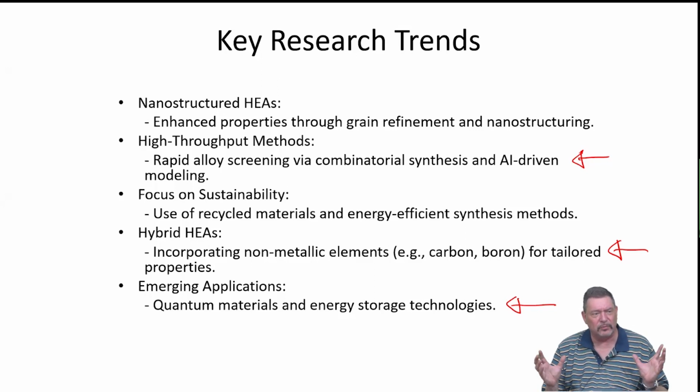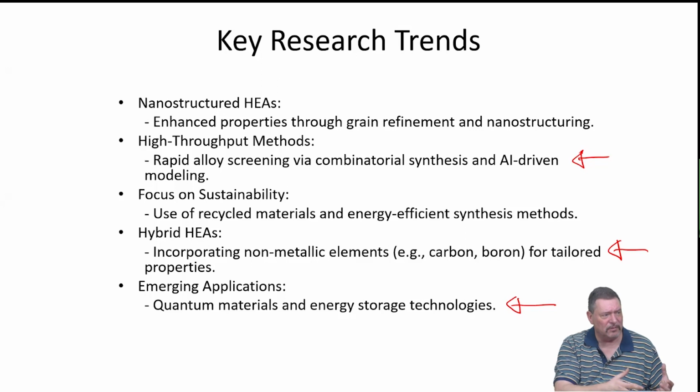then you have to take into account that the thin film is not the bulk material. It's even not a coating, right? So the properties are much more influenced by coherency stresses with the interface, with having a very huge open surface. And so all the properties which you determine are kind of dominated by different effects that are not present in your real material.